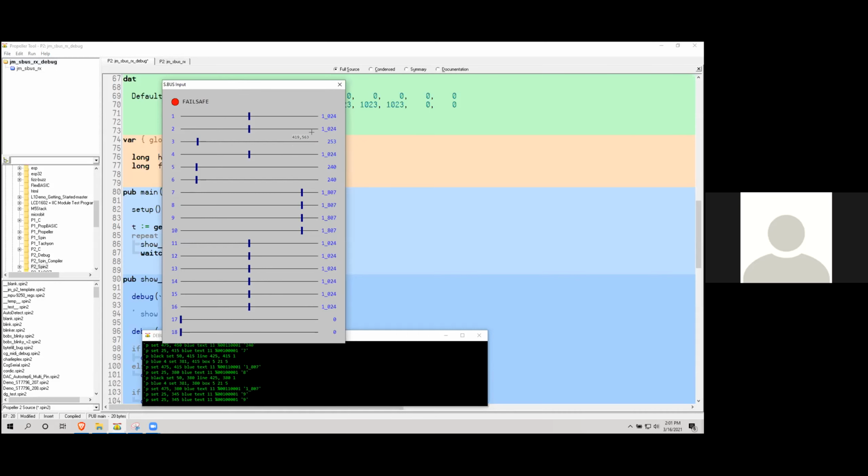What happened is that I had the throttle all the way up. You notice the throttle is at 0. In the transmitter, you can configure how it behaves in fail safe, and the default configuration that is recommended is to turn off your throttle channel and leave everything else alone. Now, the transmitter doesn't like certain configurations when I turn it on, so you'll hear it squawk when I turn it back on. I have to reset all the switches to the off position and the throttle to off, and then it will allow it to start transmitting the new values.